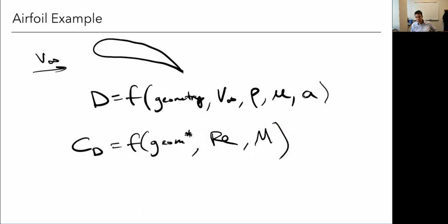If gravity is important, which doesn't apply in most of aerodynamics, buoyancy is negligible. But if we had a dirigible, an airship, where we're at low speeds, very high volumes, then the gravity term might matter, in which case the Froude number would be important. If there's unsteadiness, we'd have a Strouhal number.